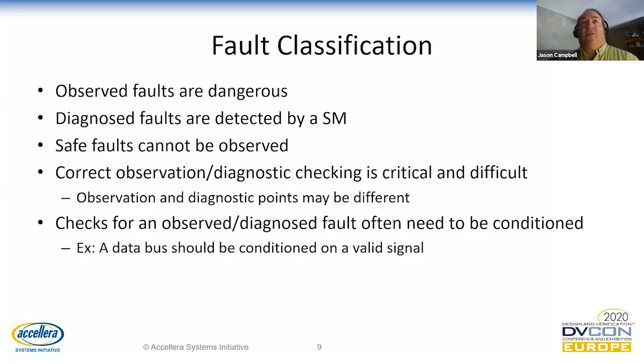So we're looking at every cycle on a data bus, and we see that a particular fault becomes observed because all that fault did was, let's say, slip the cycle count by 3. So it showed a difference, but it didn't necessarily matter. If we look at the final result, we got that final result maybe 3 cycles later, but that's within our tolerance, so that's not a problem. So if we call that fault observed, we may classify it as dangerous and not diagnosed, which counts against us.